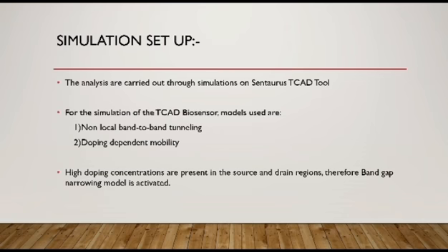This is a simulation setup for CG-TFET and HJ-TFET used in the Centaurus TCAD tool for simulation purposes. For the simulation of the biosensor, models such as non-local band-to-band tunneling and doping-dependent mobility are used, and high doping concentration is present in the source and drain regions. Therefore, the band-gap narrowing model is activated.